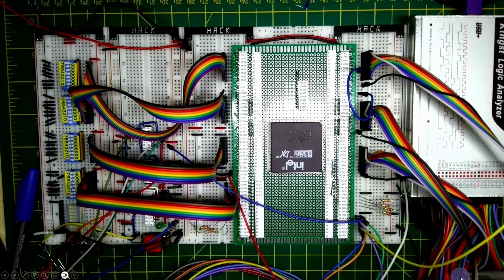Welcome to breadboarding. In the previous video we managed to get our 386 breadboard adapter all wired up and tested, and we installed it in our test breadboard here. With it we've got a power supervisor reset circuit, a 16 MHz oscillator and some additional clock circuitry to drive the CPU. We've also got dip switches to allow us to set all the data values for all 32 data bits. I've also connected a 32-channel logic analyzer which is connected to all the address signals of interest and a couple of the control lines as well.